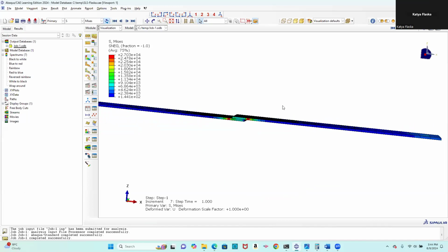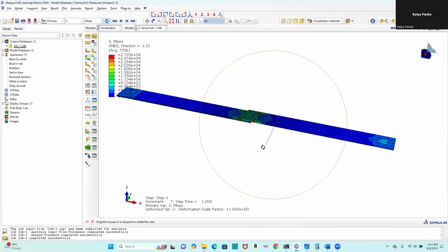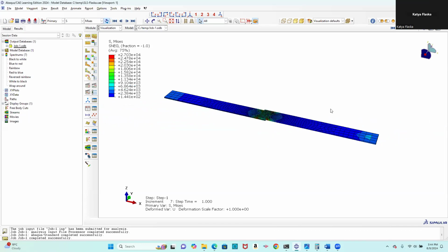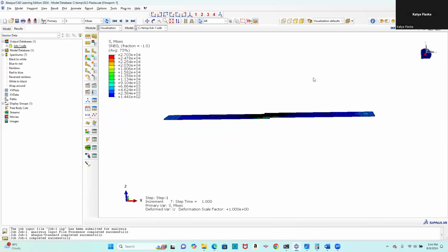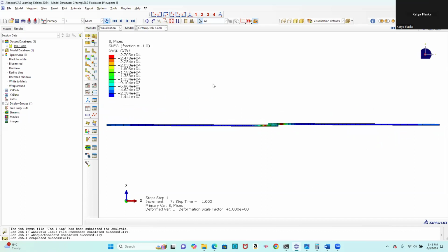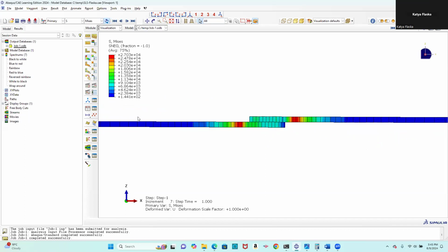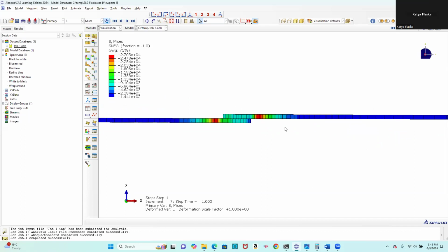And there's a lot of improvements that could be made on this model. You can see edge effects here due to what you would have the machine pulling on those ends. And like I said, you would want to model the adhesive failure, but this is a good starting point to begin to understand the adhesive behavior between 2 coupons in a lab shear test.